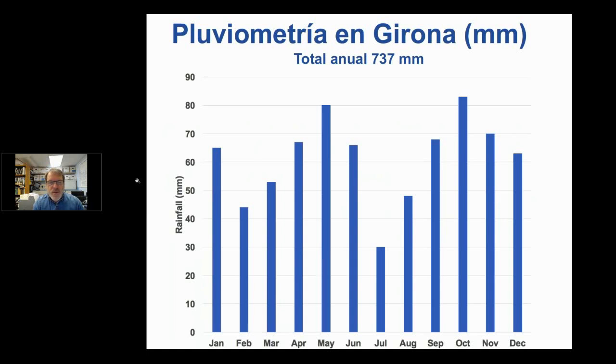You've seen this graph already. So we're looking at annual rainfall, and you should have this roughly for your location because it will help determine how much water you're going to end up using for irrigation and how much leaching impact this rainfall will have. And earlier we said that if we get 60 millimeters, we have a pretty good impact on soil salt conditions. So areas where you're getting under 60 millimeters in a month, it's going to be a little bit more difficult to manage salts. You're going to have to manage the salts with the irrigation water only. The months that we anticipate there being a problem will be July and August up in this area of the country, because these are the two times when you're going to have very low rainfall.